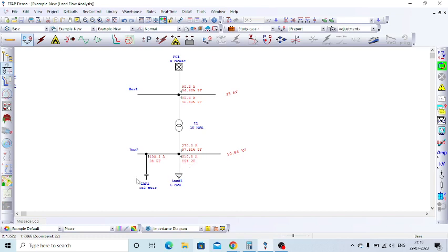In that, closer to 2 mvar, reactive power is supplied locally by the capacitor bank, so that the operating power factor is improved at the source point. Earlier it was 82 percentage, now it is increased to 96.4 percentage. So this is called reactive power compensation.